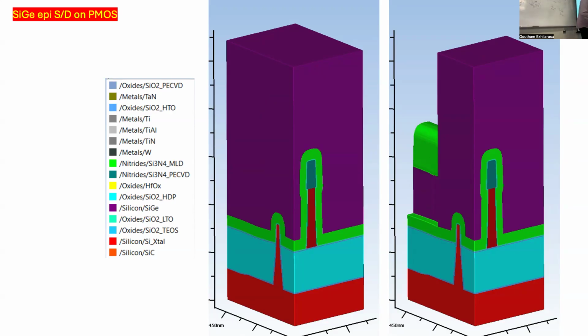What is the reason that you cut the gate? Because for example, for the inverter. No, it's an option. I just want to show that it's an option to cut the gate. You don't have to cut the gate. Just like how you can first create a fin and then you cut the fin where you don't want, right? Similarly, because it's mentioned in your PDF document, you have a cut mask for the fin, you have a cut mask for the gate also. So I want to explain what the cut mask is for.